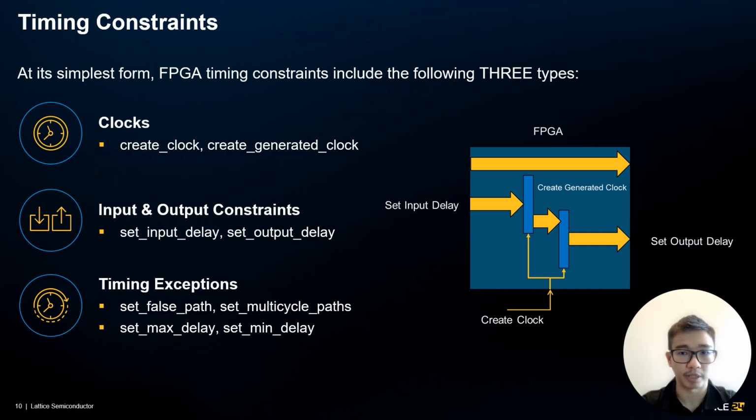The first one being to define a clock coming into the FPGA, while the second usage is when the constraint does not have a target, which means that this is a virtual clock, which is typically used for input-output, or I/O, analysis. We also have the constraint create_generated_clock, which is used to create clocks derived from a primary clock source. Some common use cases are the output of clock dividers, clock multiplexers, source synchronous outputs, and even ripple clocks.